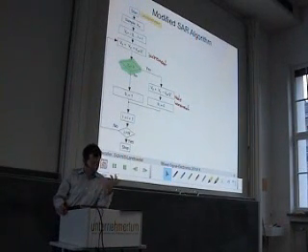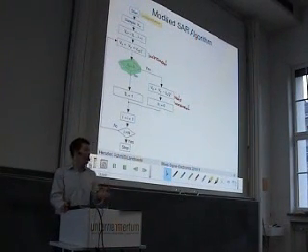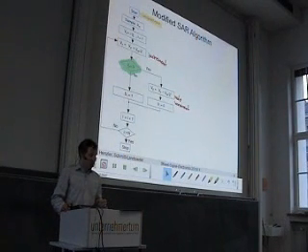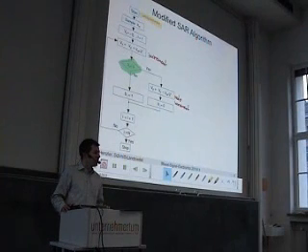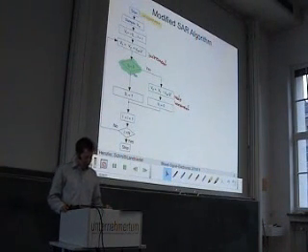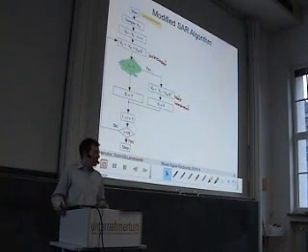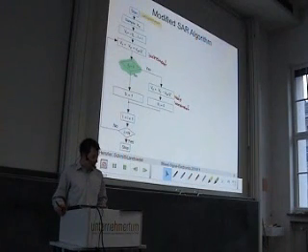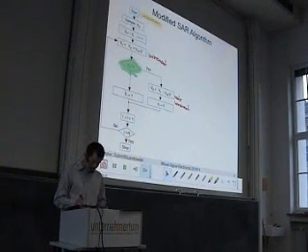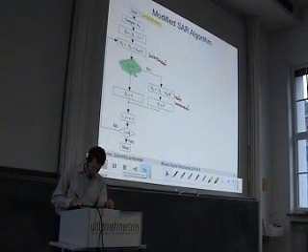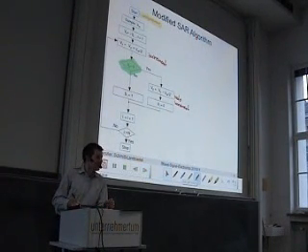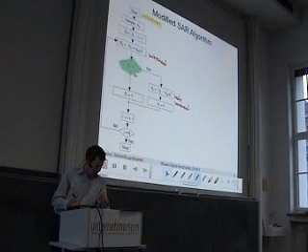If you compare always against the 0, then you have a constant reference, and you can design the comparator especially for this case, and not for a wide variability of the input common mode. So, hence, for implementation, this is much easier, and we will see that this one fits also very well to a SAR architecture that I will describe now.